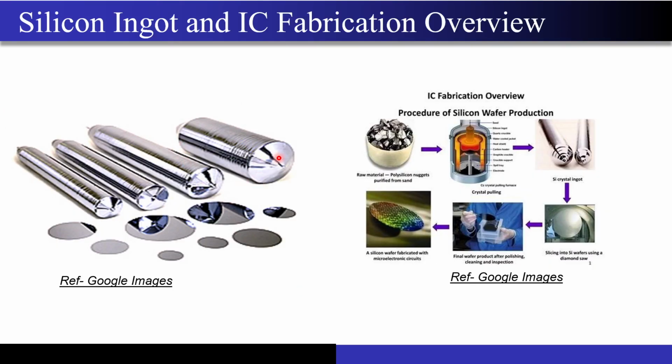So I won't go into great detail. I guess it must be clear to you how from the silicon we fabricate the dies. You take the silicon, then with the Czochralski process you create ingots of this silicon, right? You basically rotate the mixture and you get cylindrical-shaped ingots, right?